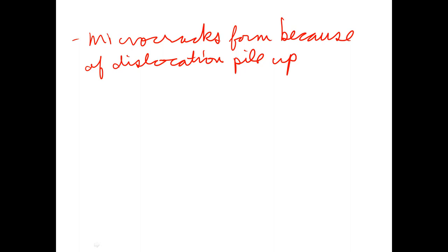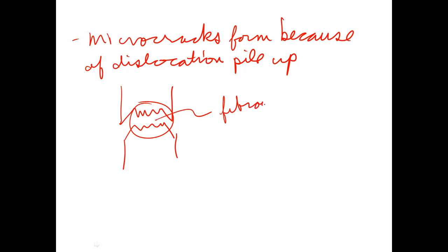Generally, under most conditions, those microcracks will form a macro crack, and then you'll get the classic cup and cone type failure surface. It's often indicative in the center region where it's fibrous in nature, which is an obvious ductile fracture surface.